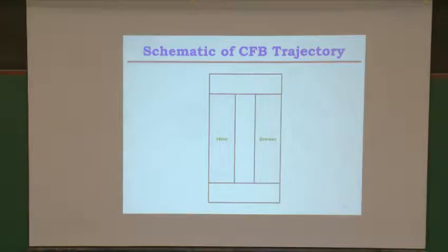So this shows a schematic of the CFD trajectory. This is using about 1,000 particles in the simulation. So this is the blue particle, which is the fresh particle that was introduced into the downer. Then it goes over here into this zone, which is not out of that zone, so we're able to mark it. We want to record when it's in the proper zone and when it's not. So we want to keep track if it comes back out over there. We don't want to record that as a true passage time. It then goes back into the system, so we want to count that as a proper passage time.